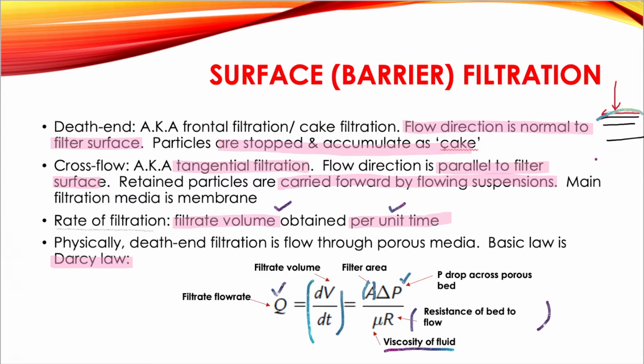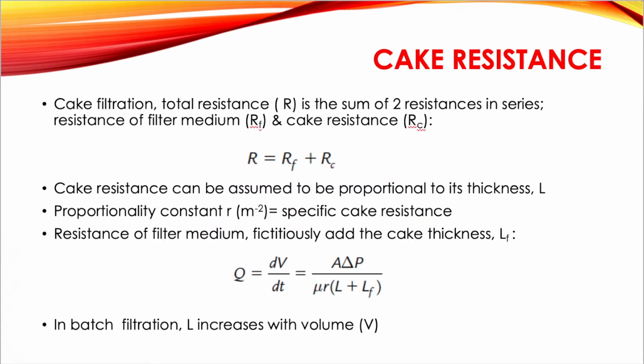This will affect the efficiency of the filtration when the cake is thick. Cake resistance or cake filtration: the total resistance is the sum of two resistances in series, the resistance of the filter medium, RF, and the cake resistance, RC. So R equals RF plus RC.